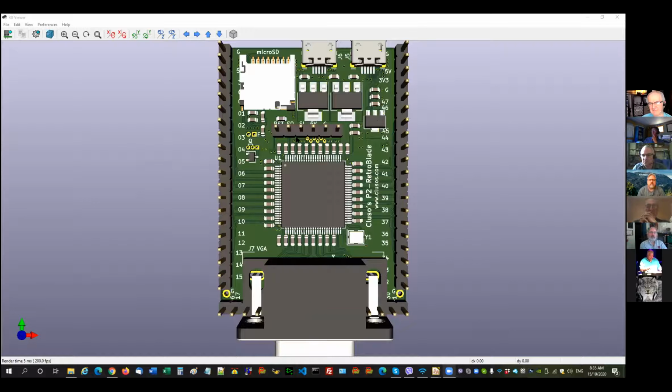Okay, the next 4. They're the 4 that go to the micro USB and to the flash chip on the other side. And then of course you've got the last pair, 62 and 63, and they're brought out on these two pins here for serial out, serial in for your typical USB connection using that CP2102. So that's where all the pins are.